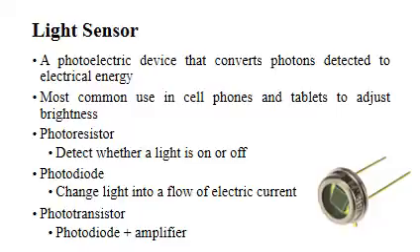The phototransistor light sensor can be described as a photodiode plus amplifier. With the added amplification, light sensitivity is far better on the phototransistors. However, it doesn't fare better in low light level detection as compared to photodiodes.